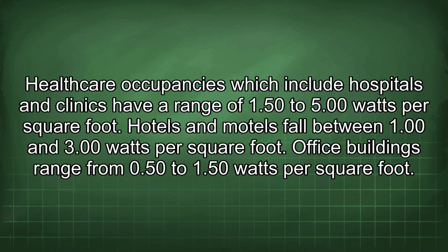Healthcare occupancies, which include hospitals and clinics, have a range of 1.50 to 5.0 watts per square foot. Hotels and motels fall between 1.0 and 3.0 watts per square foot. Office buildings range from 0.50 to 1.50 watts per square foot.